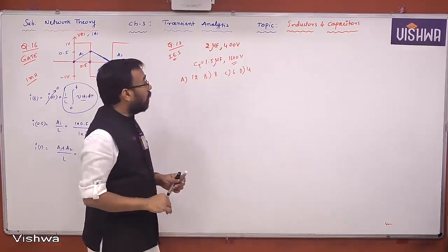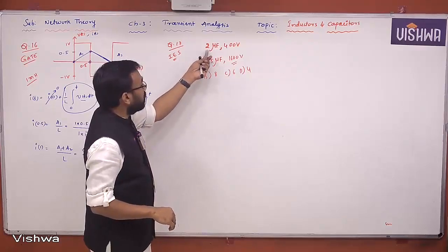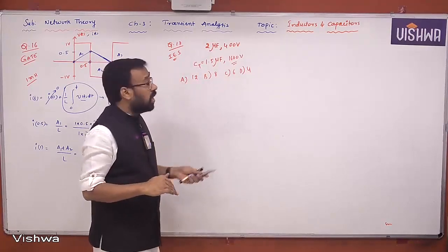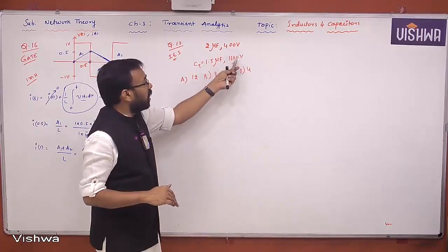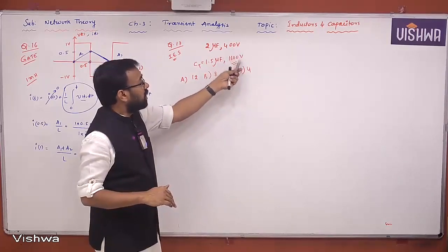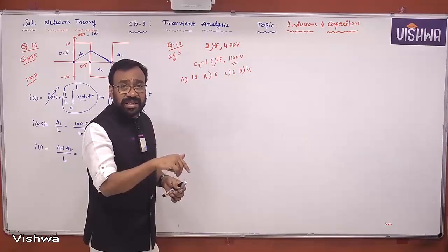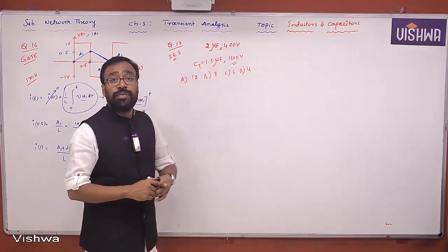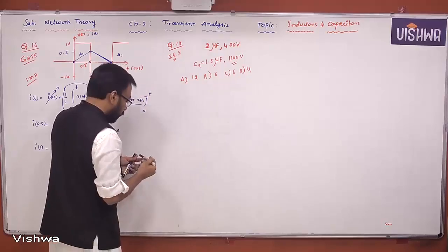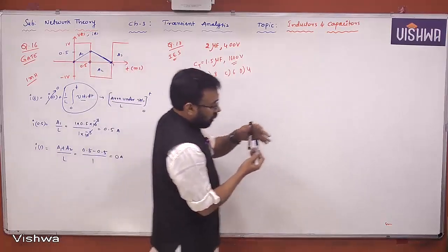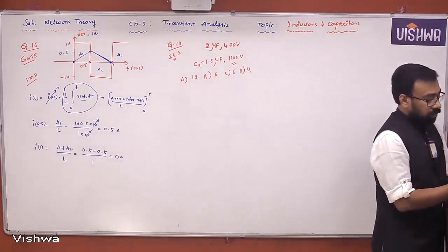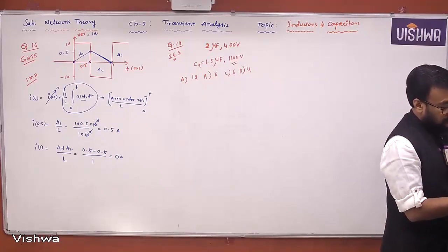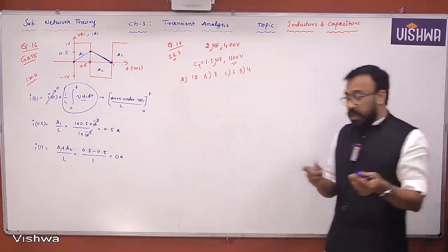Okay. Well, but when you go for a series combination of capacitors, the capacitance value will decrease. Yes or no? How many capacitors are required to be connected in series to get 1600 volts? Definitely 400 into 4, so a total of 4 capacitors are required. Yes or no, all of you? Okay. So therefore here, let me draw it clearly.